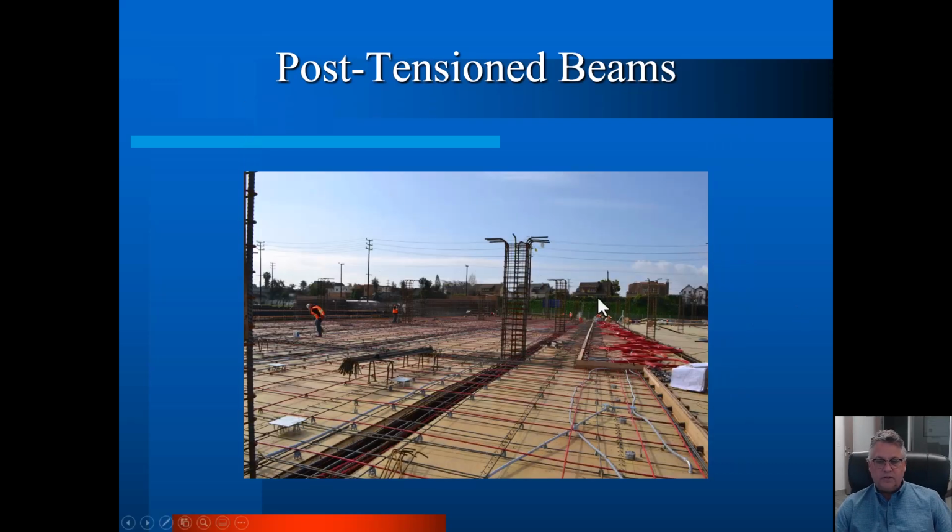This is the top of the system. These are the beams. These are the forms. These are formed by those steel beam forms. And these are the slabs spanning one way, beam to beam to beam. There's a girder in here picking up. This is going to be the turnaround aisle where the cars turn. But the slabs and the beams in long span post-tension structures, most post-tension structures, they're post-tension in both directions. So slabs in one direction, beams in the other direction.